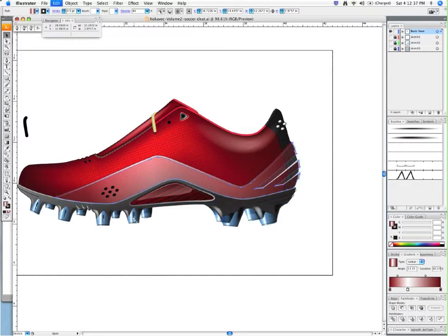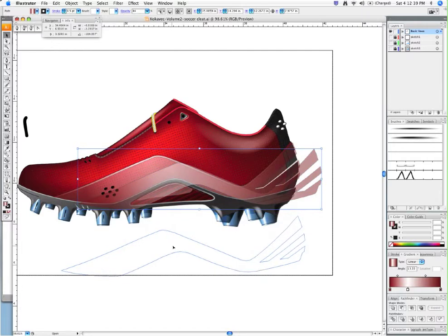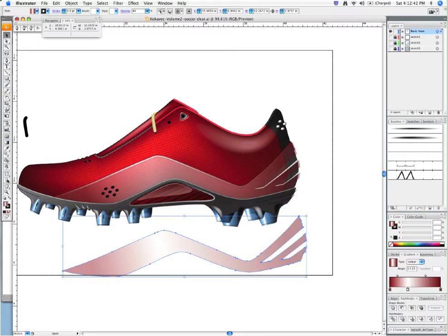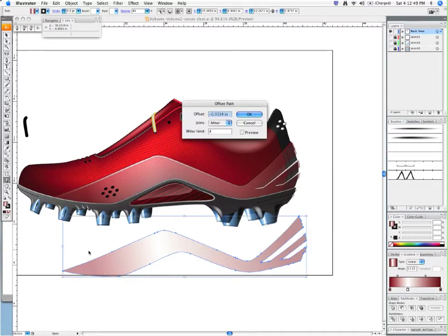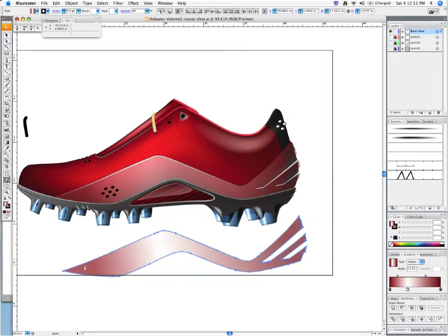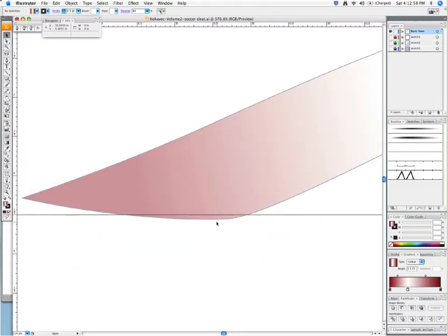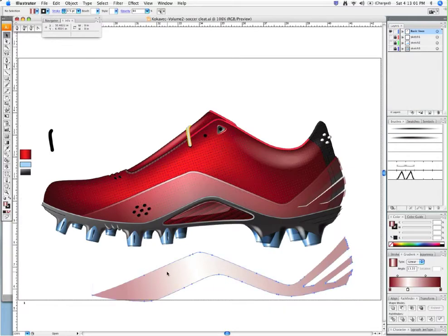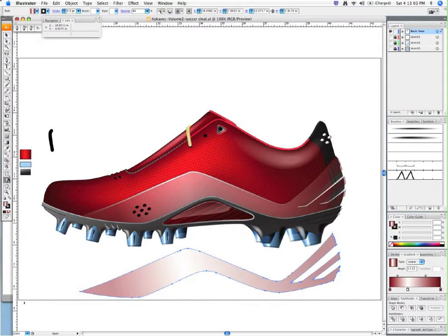Now let's go ahead and copy and paste this. Let's do that down here as well. So let's go with that knife tool, and let's offset this -0.5 millimeters, just a tad. And we'll grab the inside, keep the inside, and I like the knife tool because it's almost a little bit more of a random effect. I'm just going to come down, and whatever you have selected